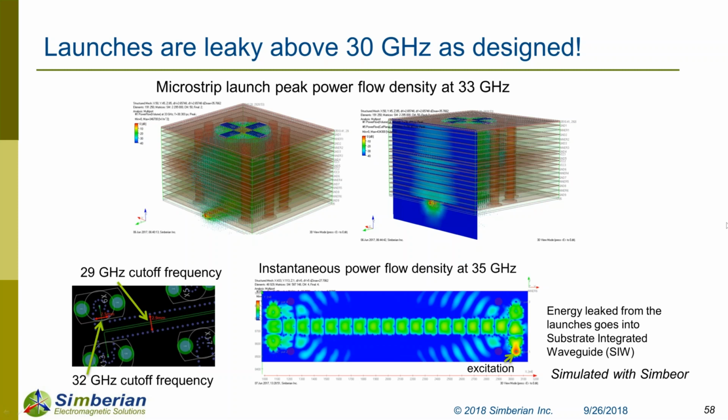Yeah, I can just add, Yuri, to the discussion you brought up. We have seen this for 28 gigabaud signals. You have a null at 28 gigahertz. Depending on whether you use NRZ or PAM4, we had this resonance at 33 gigahertz. According to all these rules of thumb, it shouldn't matter. It's way beyond 14 gigahertz, the Nyquist. Well, it's different. Now that PAM4 is finally coming out, we're going to see some issues. We cannot just extend this reasoning we had for NRZ to PAM4 without paying the price. So we have to have much more control higher up in the frequency.